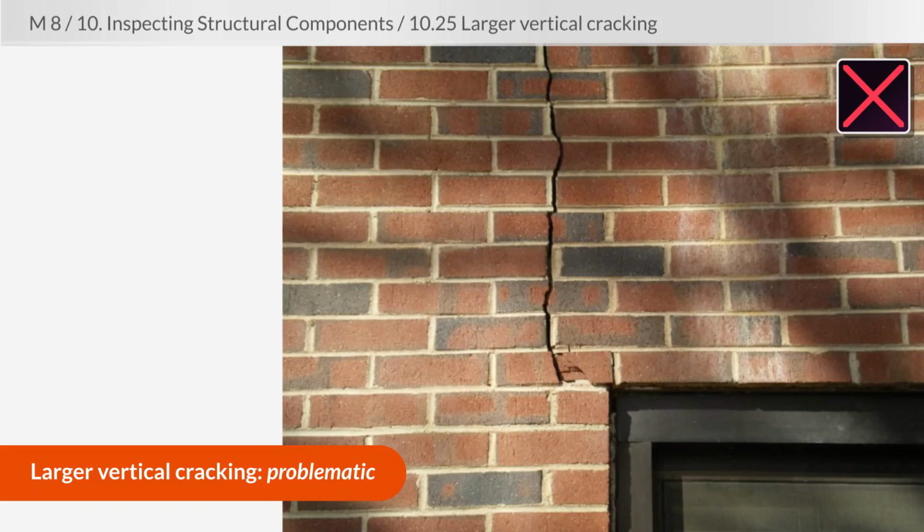This is a good example now of a crack, and you're not 100% sure what caused it. It comes off the top of a window. It goes up, but it doesn't go down, so it's probably not a foundation issue. Is it a problem with the lintel, which would make it an issue for a masonry contractor? It's hard to say. So, if you're not sure about something like this, then go ahead and recommend a licensed structural engineer.